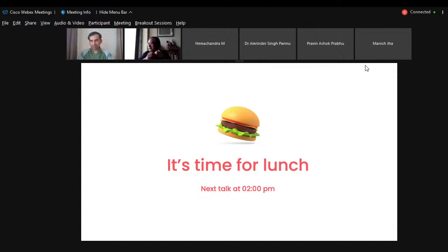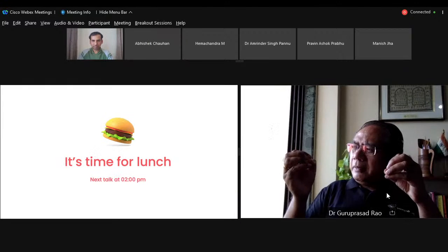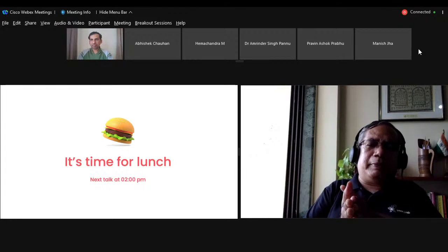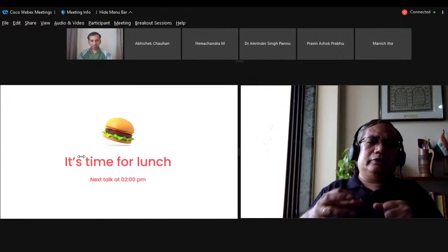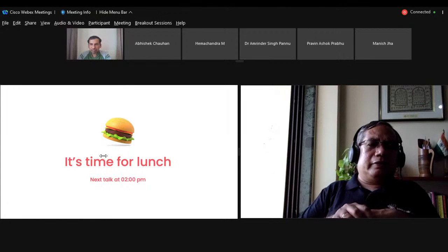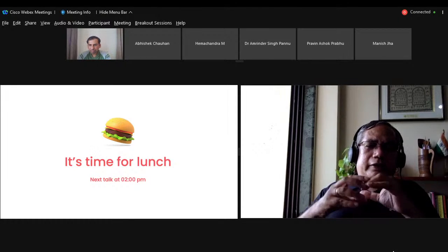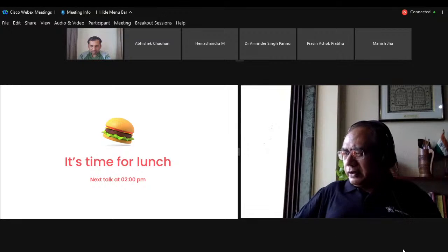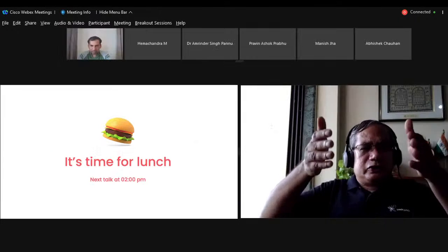What are zero processes? Like you have coining, rolling, wire drawing, hobbing, forging, and all these are kind of forming processes. They don't have material removed or added. In coining, for example, material is not removed. So it flows plastically into the cavity. That is the whole beauty of it. And so they are called zero processes.